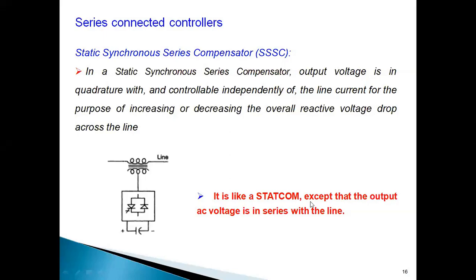Okay, let me go fast. So, static synchronous series compensator. This is similar in construction. It is the same as that of STATCOM. I'll be discussing STATCOM in detail. The only difference is that it is connected in series with the transmission line. So that is a shunt controller, and this is a series controller.